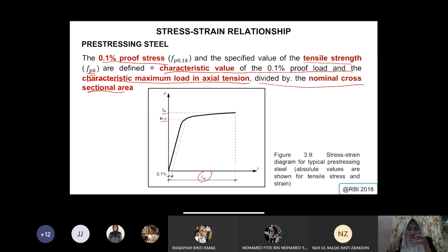So steel reinforcement and tendon are two different properties, unless you are using a bar as your tendon, but still it will give you additional strain because you pull your bar. So in terms of material, probably the same type of material, but you still have initial strain because you pull the bar, so you are applying force to that bar.